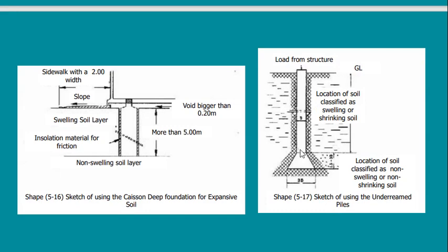This is the normal pile. They come to the last end of the pile, and they use a special machine that enlarges the void below, so that when you pour the concrete it will fill all this space. If the soil wants to expand, it will move up. The pile cap will be on top. It will push the pile cap to the top. Once it pushes the pile cap to the top, the pile will prevent the pile cap from moving because it has an enlarged base below.